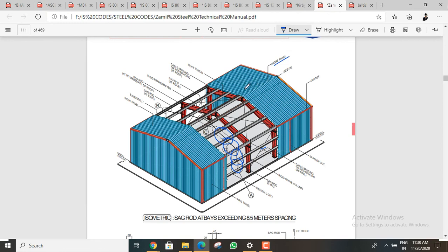Yeah, this is a ridge panel. See guys, I already explained, this is only the ridge panel, from here to here only. The same sheeting will be cut in a different shape. For action, you see here is a gutter strap, and this will be the vertical gutter. And here are the wall panels and side wall girt. So this will be the side wall girt.